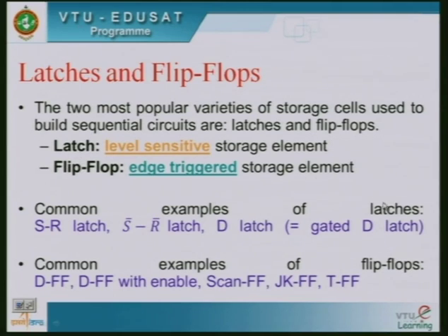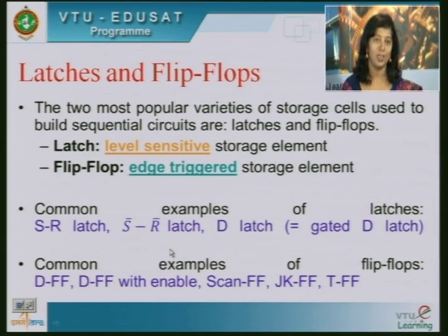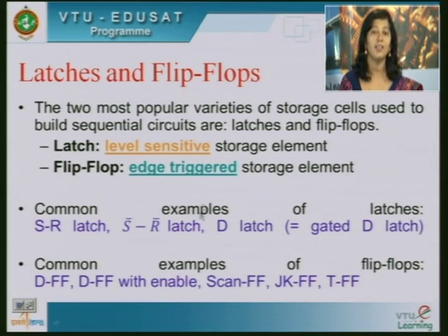Common examples of latches we study are SR latches, S bar R bar latches, that is complemented input latches, D latch, gated D latch, etc. And common examples of flip-flops are the D flip-flop, or the delay flip-flop, sometimes also known as data flip-flop, and D flip-flop with an enable input. Then we have the JK flip-flop, the toggle flip-flop, T flip-flop and so on. These are the common types of latches and flip-flops used.